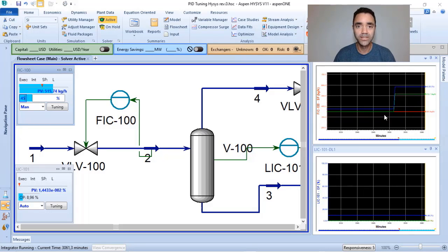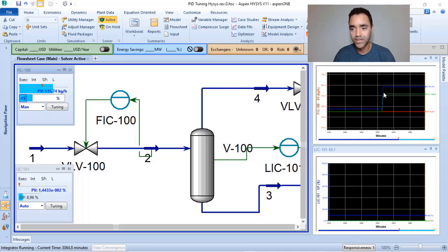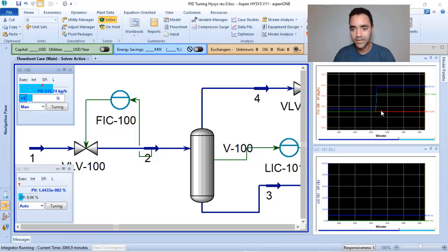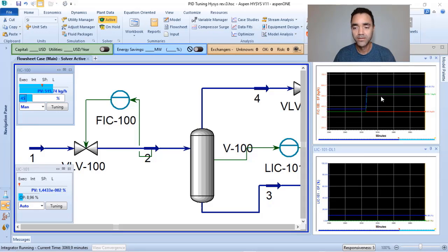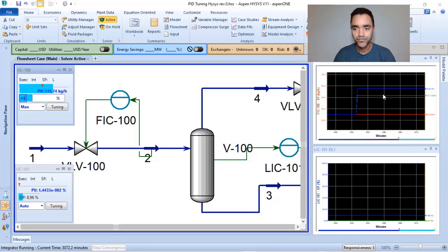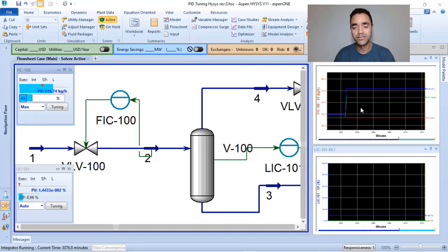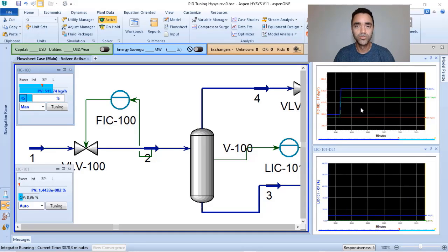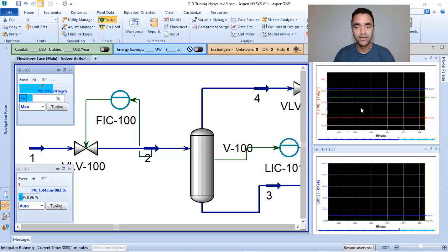I will look for the time constant and also for the gain of the process, because now the set point is not matching the present value. So this is the way that Ziegler and Nichols recommend you to define the values for the PID.